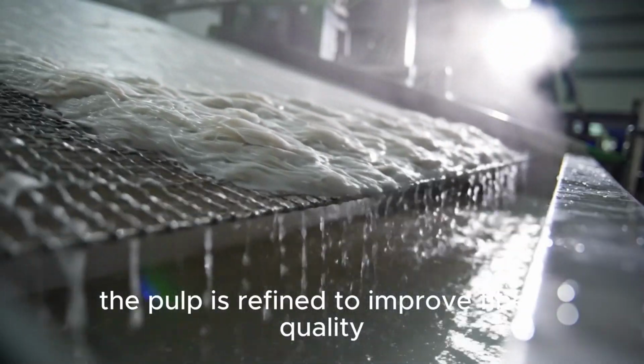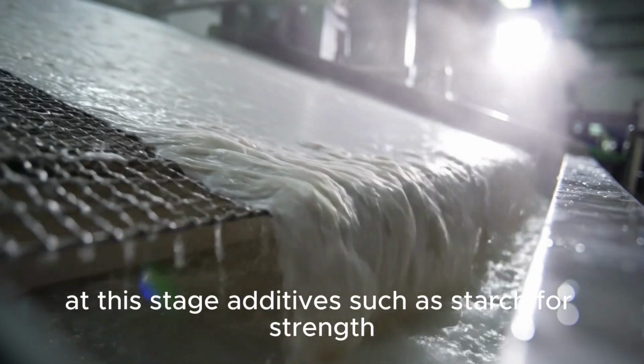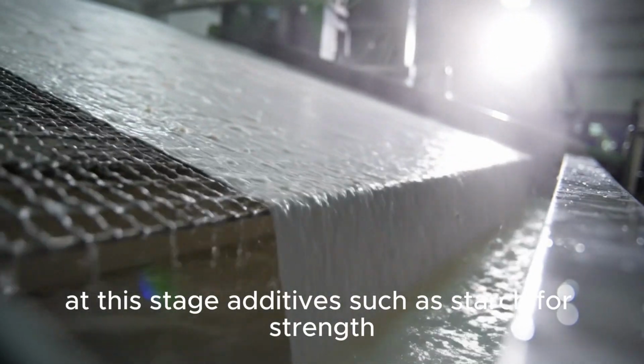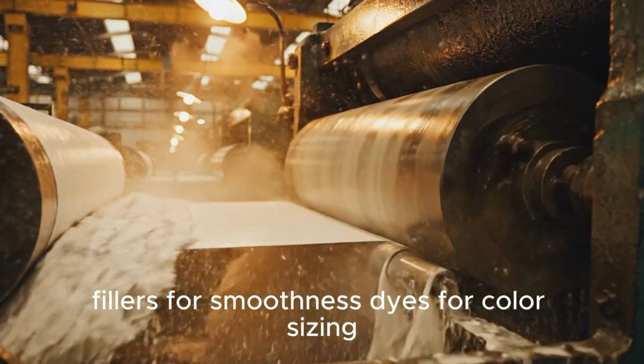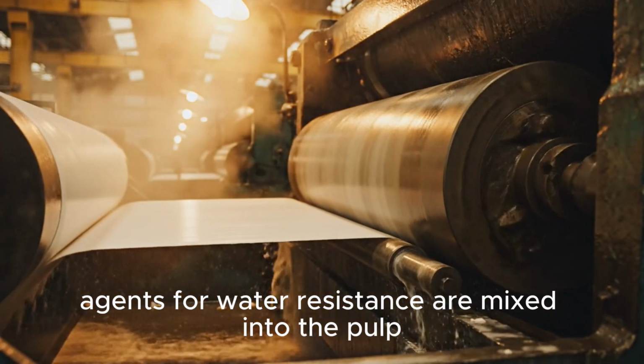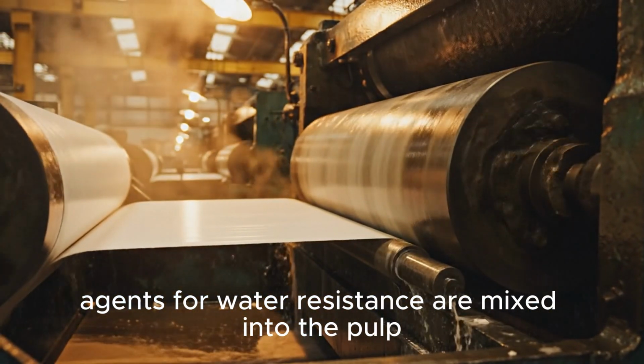Step 5. Refining and additives. The pulp is refined to improve fiber bonding. At this stage, additives such as starch for strength, fillers for smoothness, dyes for color, and sizing agents for water resistance are mixed into the pulp.